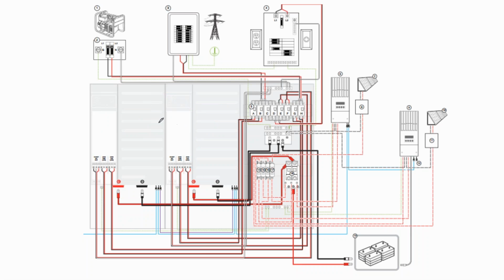You can't double stack inverters willy-nilly. What you have between these two double stacked inverters is an Ethernet port and a communication box that kind of governs the relationship between the two inverters. One inverter being what's called a master inverter, and the other inverter being a slave inverter.